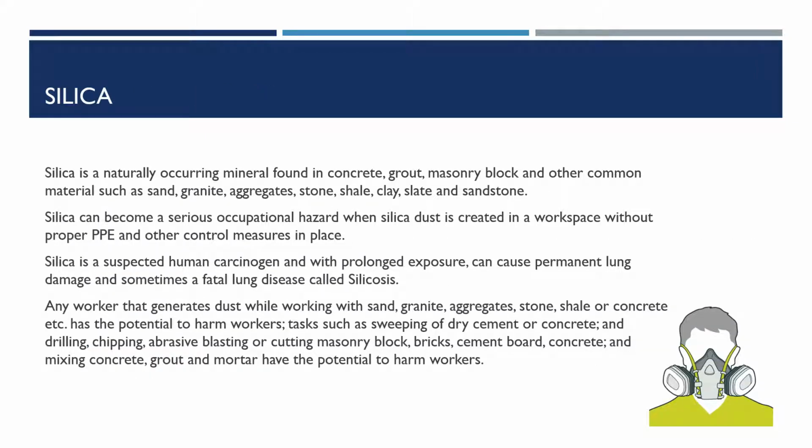Silica. Silica is a naturally occurring mineral found in concrete, grout, masonry block, and other common materials such as sand, granite, aggregates, stone, shale, clay, slate, and sandstone. Silica can become a serious occupational hazard when silica dust is created in a workspace without proper PPE and other control measures in place. Silica is a suspected human carcinogen, and with prolonged exposure can cause permanent lung damage and sometimes fatal lung disease called silicosis.